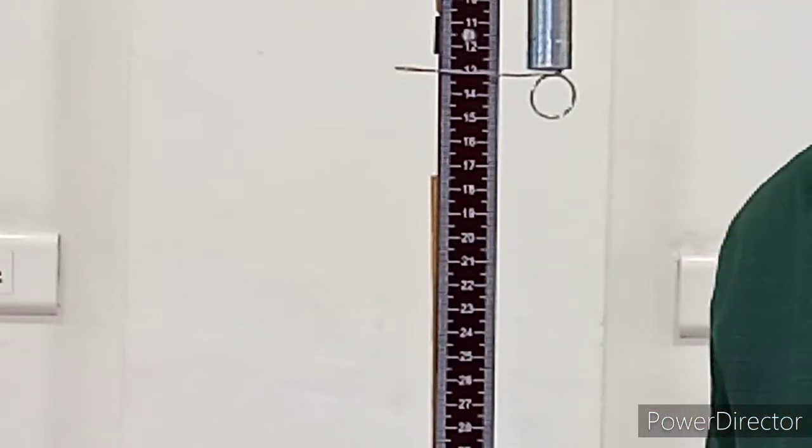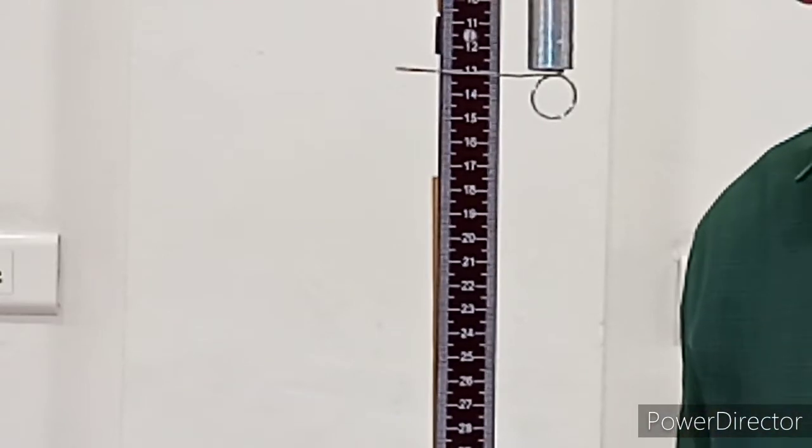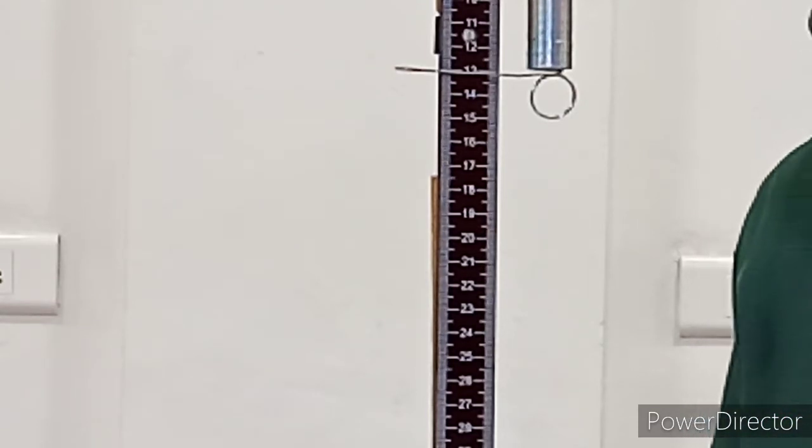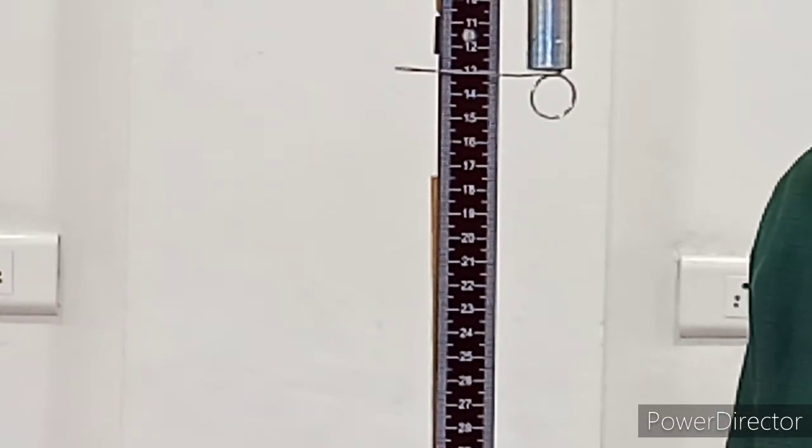In such a situation, first I will have to make a tabular column which I showed you before, which was available on the board. Once again I tell you, you will have to make a notebook to record the observations, that is, an observation notebook. As per the tabular column which I showed you, the serial number, the mass in kilograms and the load in Newton, the position of the pointer has to be noted while the loads are attached first, followed by detached next, and the mean value of the reading we have to note down in another column, followed by the extension L in centimeter and meter in separate columns.